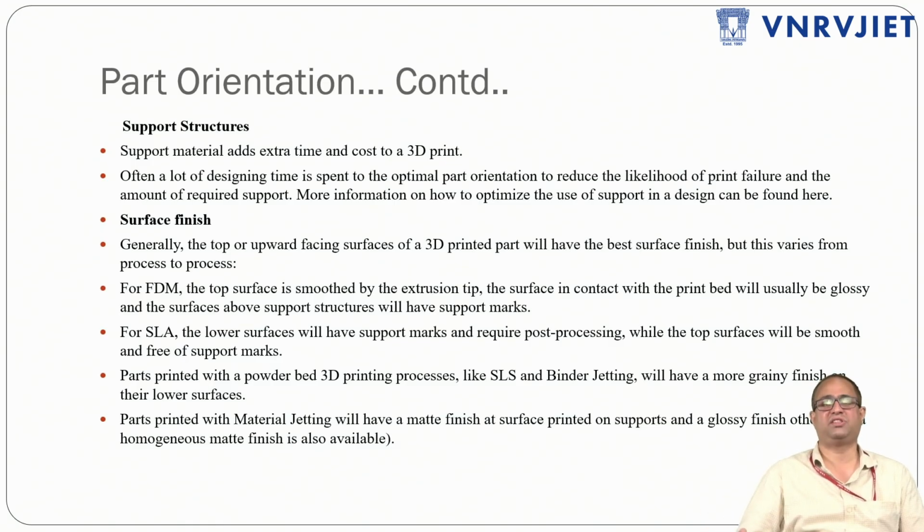The building can't withstand, just like that. So supports are going to act as the pillars for the parts to be printed. At the same time, if you remove the supports completely, the part is going to collapse. So in this case, we need to optimize the supports.